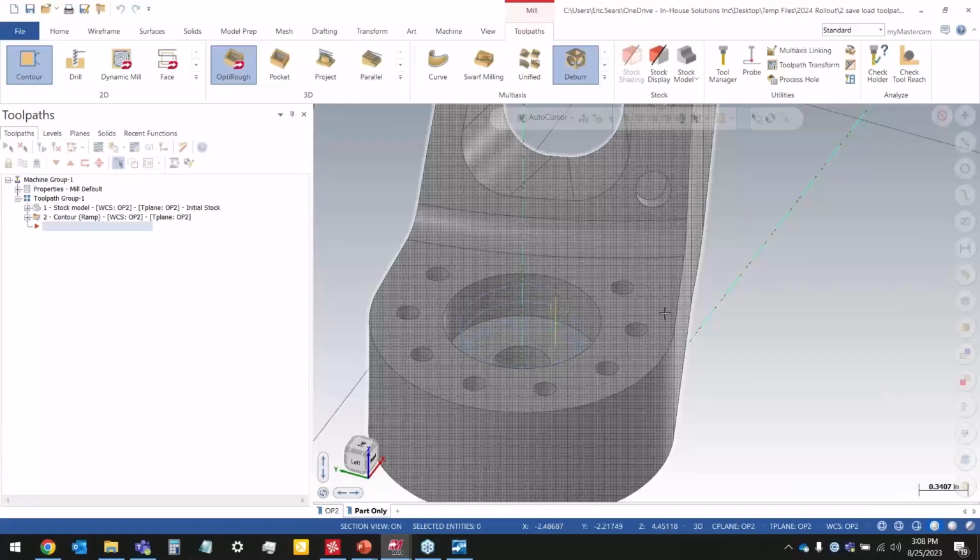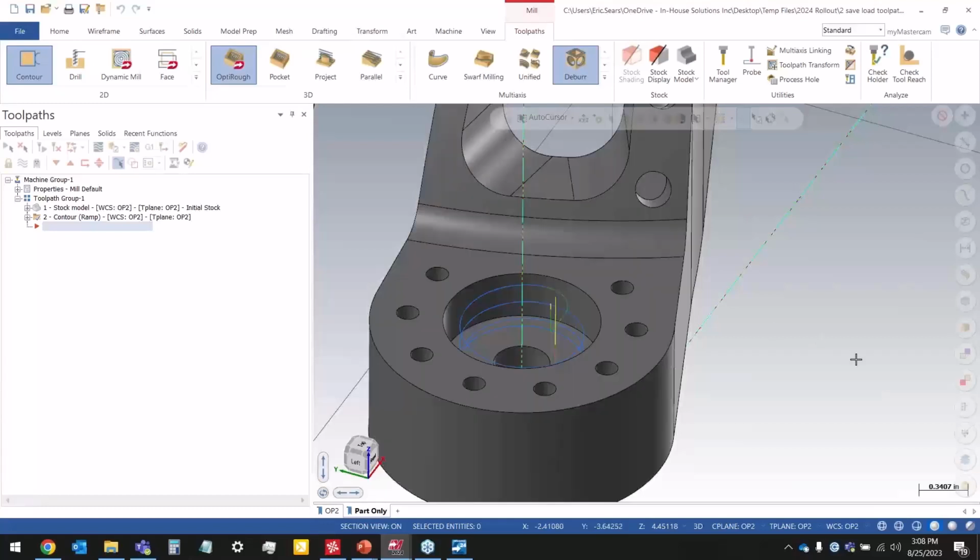And then there was this one going back to David, when you were showing off the trimming of the entities. The question is, can you change the settings so that the sides you want to trim will be removed? My guess is that's going to be trim divide. But if you were selecting, you always have to select what you want to remain. Exactly. I think specific to that question it would be trim divide, because then you just click on what you want removed.